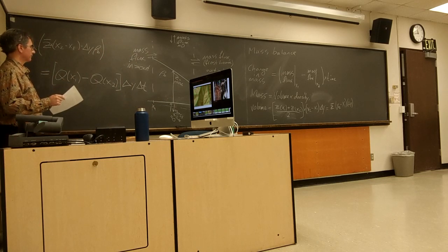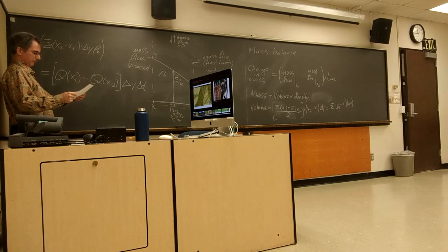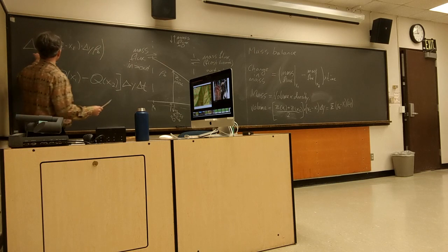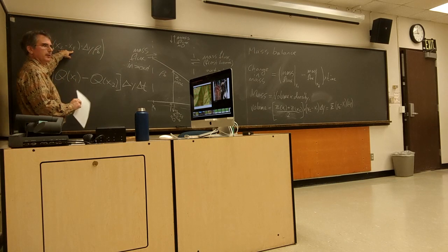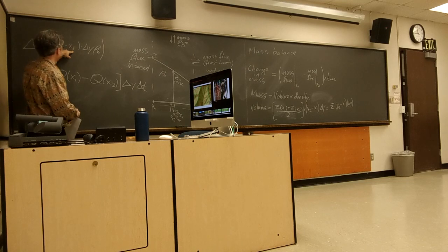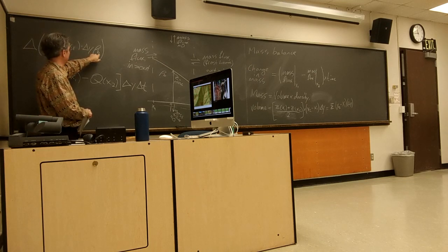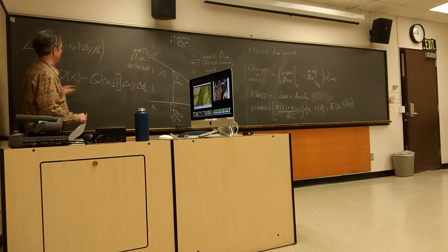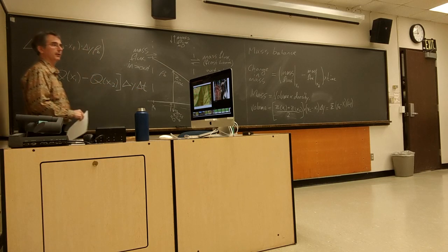All right. Well, this is a little clunky looking for my tastes, maybe yours as well. Let's do a little massaging of this. First of all, we've got some constant terms here. This increment x2 minus x1 isn't changing. We're setting that to be our control volume. Our delta y isn't changing. Our density isn't changing. So we can take those out of the delta, divide both sides by them. Similarly, divide both sides by delta t.